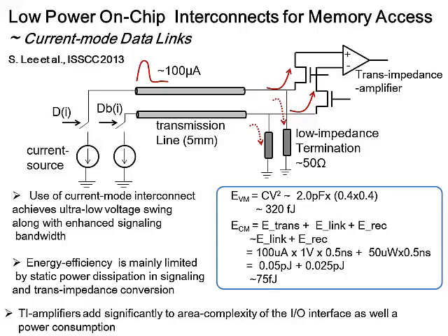In this scheme, although the CV square power dissipation on the metal line can be almost eliminated because it's a current mode transmission scheme, at the receiving end we need an analog mode transimpedance amplifier, which again consumes a good amount of power as well as area. An optimized design in 45 nanometer CMOS technology gives us around 3x power benefit as compared to the conventional method.